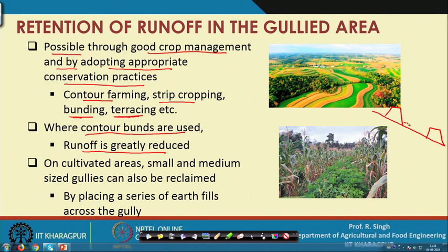then obviously this particular area acts as a catchment area in between these 2 contours. So, whatever rainfall occurs there, we would focus on retaining that over that particular area. We do not allow water to flow away. So, that is why runoff is controlled or runoff is completely conserved within the contour area.